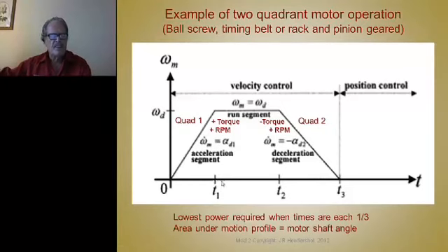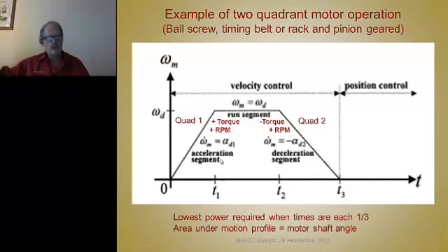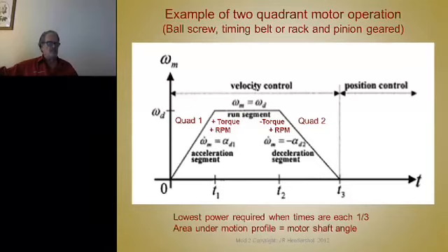So a third of the time, to make the trapezoid approximately the same shape, we could accelerate slower. We would come up like this and hit a point, and then decide we have to stop, and then reverse torque, make torque negative, and stop and come down till we get to here. So we'd have a triangular move where the area in this peak of the triangle equals the two areas we lose over here. Now, if I could accelerate in 0 time